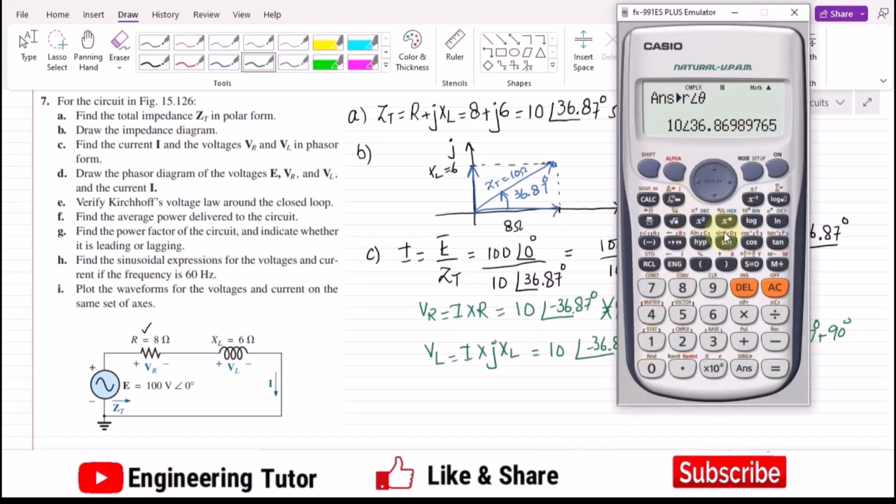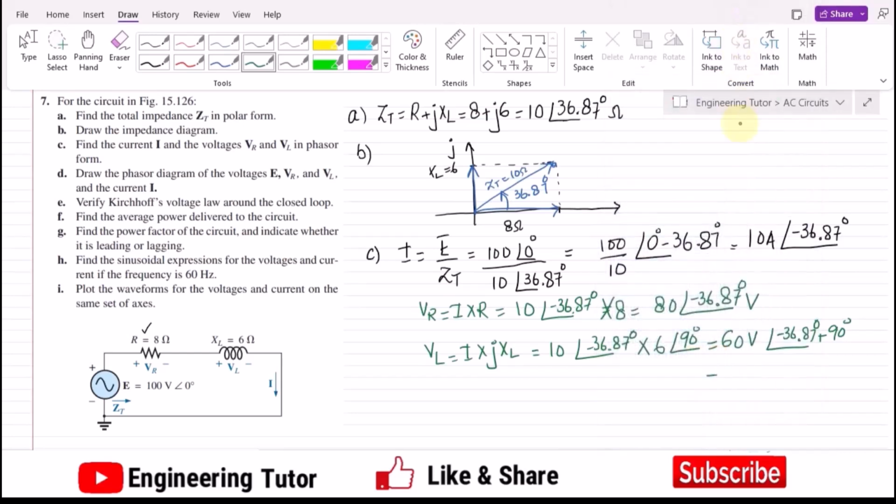So how much would it be? 90 minus 36.87 is 53.13 degrees, as it is plus here. So that is the value of the voltage across the inductor, 60 volts at 53.13 degrees. This is part C, in which we have found all the values we had to find.